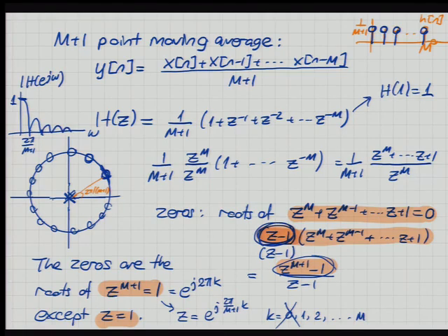All right? So it's a low pass filter clearly because it passes high frequencies. I'm sorry, low frequencies. And then higher frequencies are getting eliminated. It is not a monotone response. It's not that, as omega increases, the response is gradually decreasing. It tries to go back up and then comes back down again. All right? But it's very interesting. So you look at the structure of the difference equation. You turn it into a transfer function. The zeros of that happen to be uniformly distributed on the circle, and they stop a bunch of frequencies, and that's why you get that frequency response. So I think all those connections are quite fascinating. We can link anything to anything, right? The difference equation to impulse response, to Z transform, and to frequency response, poles, zeros, everything goes together.